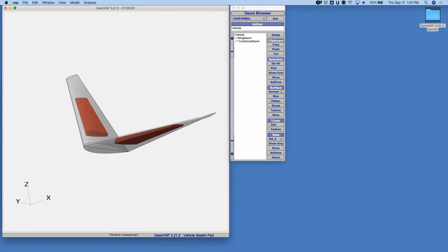And I would go so far as to say, maybe really go to extreme lengths. Just ignore the airfoil and use a NACA airfoil. Get the leading edge matched up, get the trailing edge matched up, and get to where you're very, very happy with those. Once you've done that, sort of to Andy Hahn's point, once you're close on the wing, Fit Model's job is a lot easier. So once you're close there, and if you knew it was one of the existing airfoil families, certainly use that family. But I would start by simply trying to match the thickness and get the thickness about right, and then maybe match the rest of the shape.